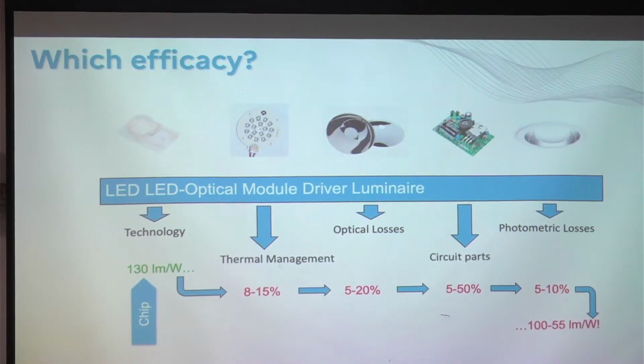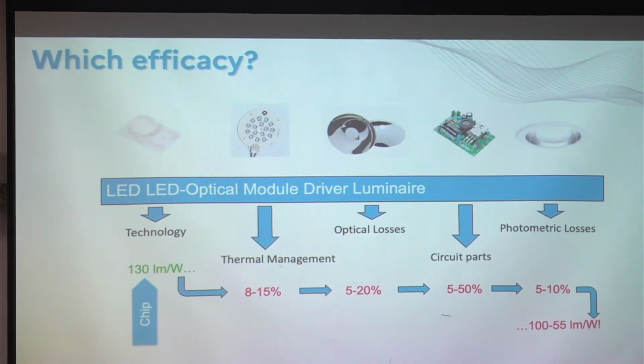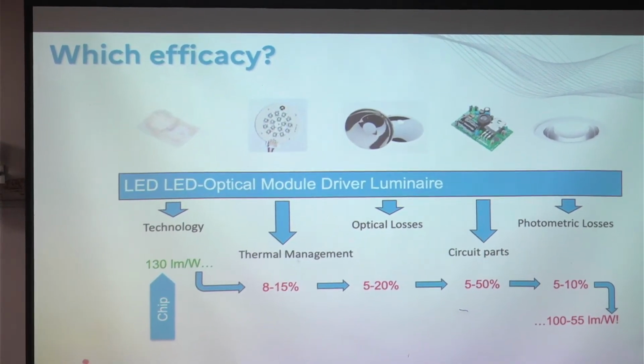And when you make lighting, I don't care about that. I'm interested in that. Many people today, unscrupulous people, sell LED systems and show calculations using the value in lumens per watt of the chip that they integrate in the system, and never the real value of the system. When I see lighting systems like that and the guy tells me 150 lumens per watt, I don't believe him. A system like that can achieve maybe today 100, 120 lumens per watt, except if you have 300 lumens per watt LEDs behind, but this doesn't exist today.